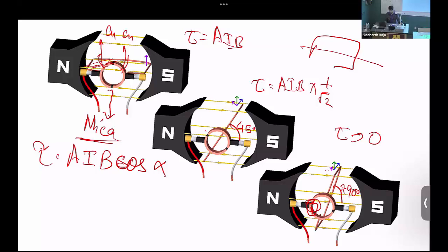What do you do if the rotor stops at that position where the windings are shorted? Rotor stops in this position. Nothing would happen though. We will see how the current, when the winding is shorted. In this case, we are looking at just one single conductor, so one single conductor will become a problem, right? If you have just a single loop, you have to physically turn it around so that it starts rotating. But in a typical motor, you won't have one single conductor, you will distribute the windings around. So there will always be a bunch of conductors which will have some torque being produced, right? Any other questions?